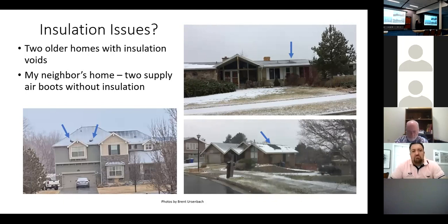What's this? More insulation, the attic space. Well, maybe. It does have to do with insulation. Heat losses come out of the attic space and melt the snow off. It is, but guess what's exactly there? 2 supply air boots. They're facing the wrong direction. No, they're not sealed properly. Which is R8.